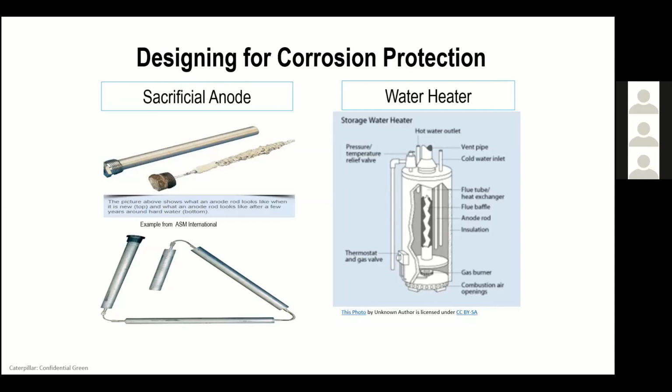the ability to remove it. Sometimes it's a little harder on others, but it's roughly, I think it's standardized, maybe a 1 1/16 deep socket hex. Most of the time you're going to remove a large rod. But if you do this periodically, and depending on your water, you can really extend the life and save a lot of money, because you won't have to replace the water heater.